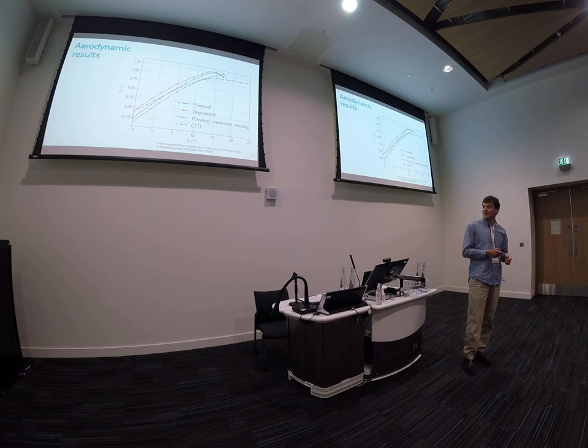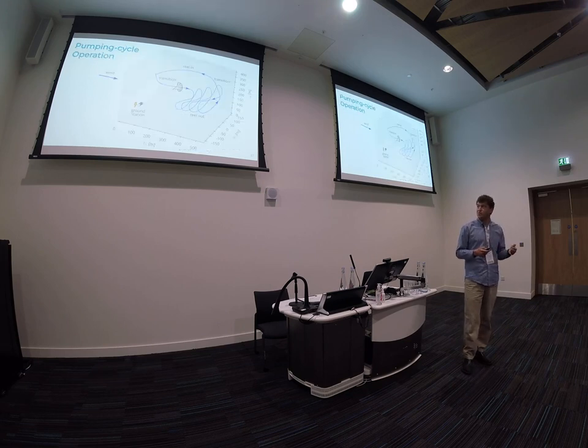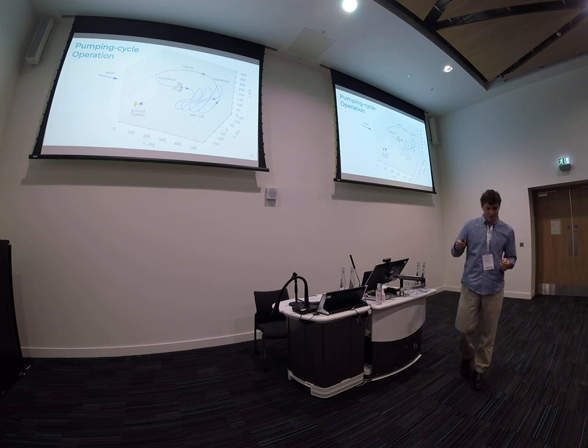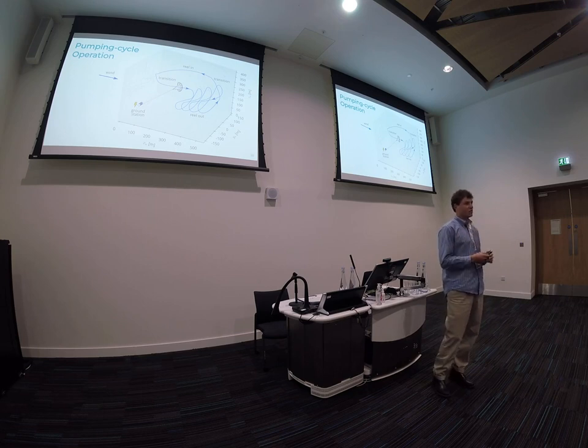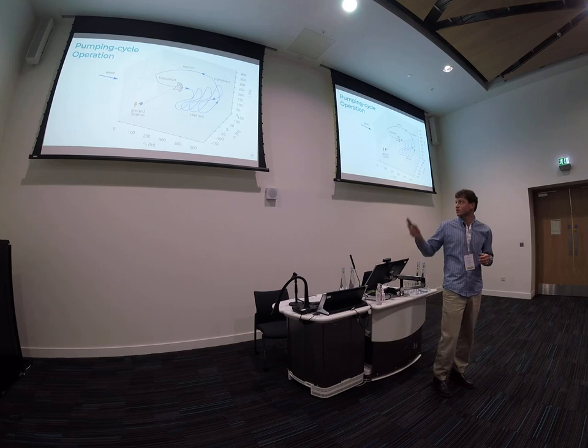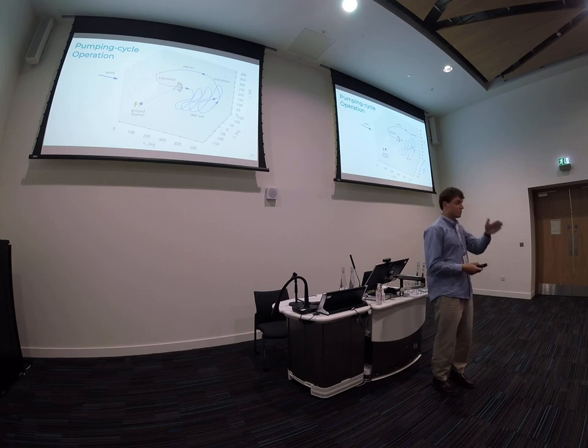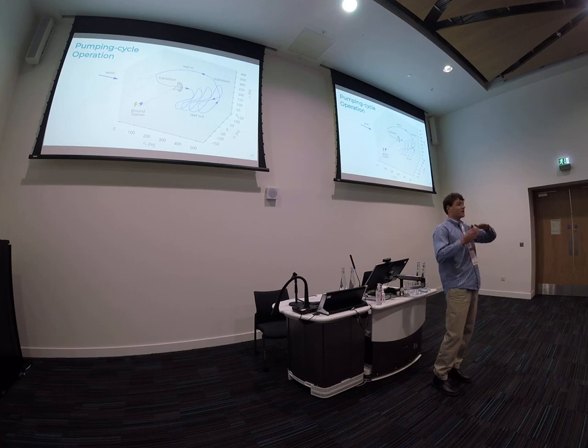And then I would like to get back to the pumping cycle again. So the simulations we did would correspond to the reel-in flight phase, or essentially operating points there. But what we can also do is look at the reel-out flight phase, which consists of straight parts going on a diagonal, though. But with some assumptions, we could say that for this straight part, also an idealized symmetric condition can hold, and that means that we can now predict or approximate how the kite's form and forces would look like during both reel-out and reel-in phase. And this gives the kite designer a lot more knowledge to make better kites.